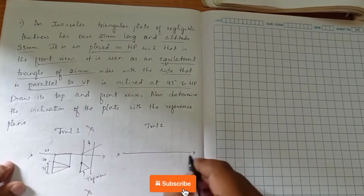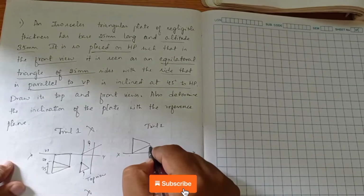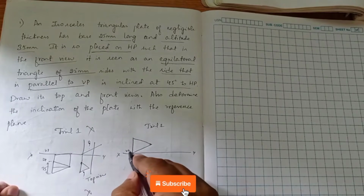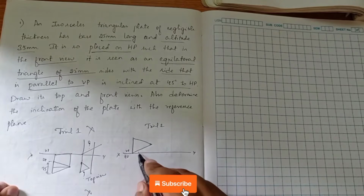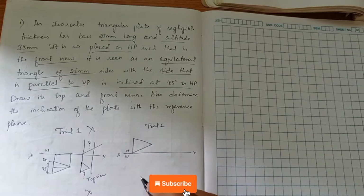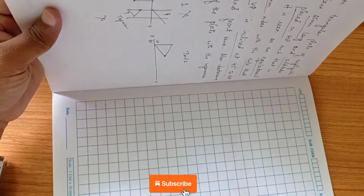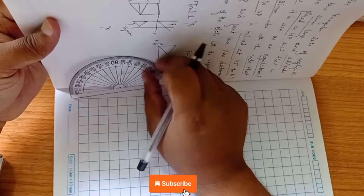You can see in this we will construct here such that one of the corners is touching. It is in the vertical plane, but one of the corners is resting on the XY line. If it is resting on the XY line, it means it is touching the HP also. It is placed like this. Say consider this is the horizontal plane, this is the vertical plane, and we have placed the equilateral triangle like this.